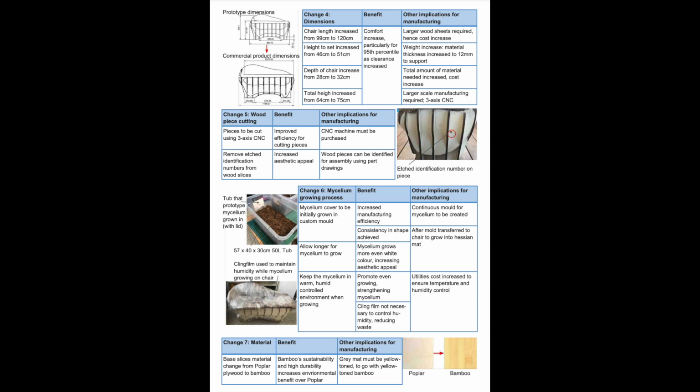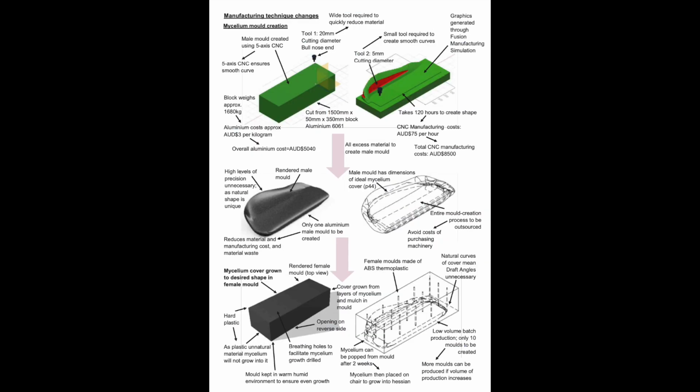The shape of the components potentially creates a huge amount of waste, which will significantly increase the cost of manufacturing and environmental impact. When thinking about the use of computer numeric control, CNC machining, the student should have considered nesting parts to reduce wastage.